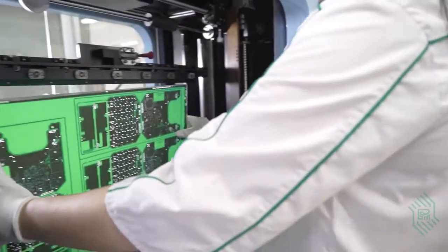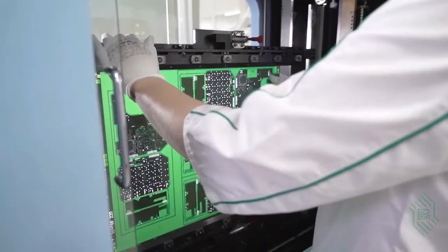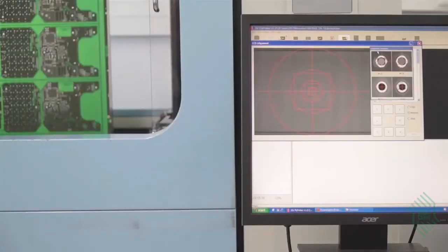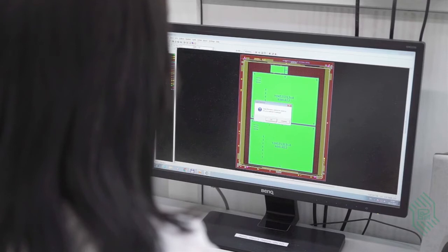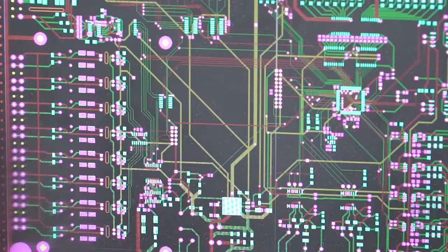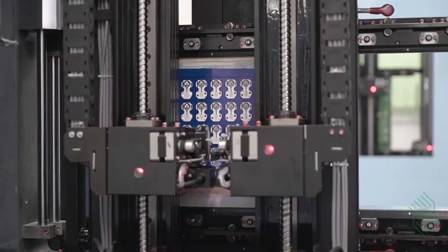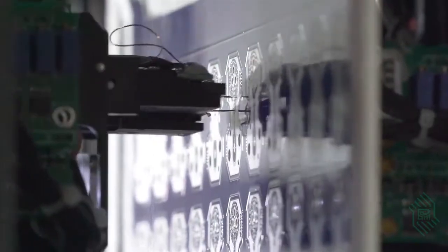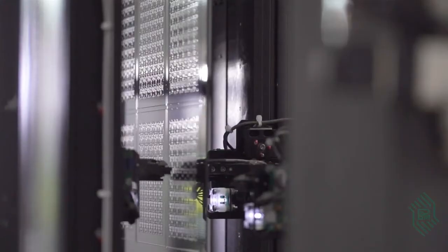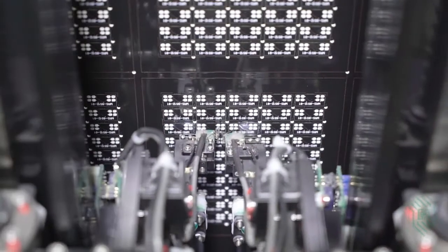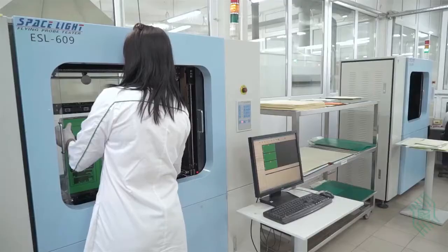The multi-layer printed circuit boards coated with a finishing coat are transferred to the electrical testing area. Using the program put together at the PCB's preparation stage, the machine verifies all nets for integrity, continuously touching the contact pads. At the second stage, the adjacent nets are checked for reciprocal contact. This test ensures that during the production process, all nets were replicated correctly.